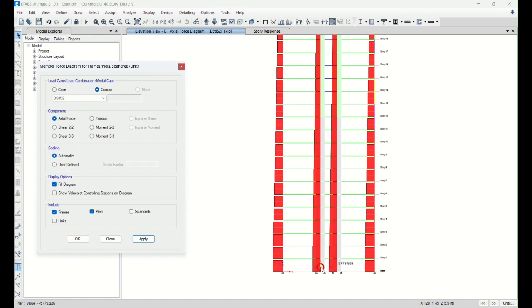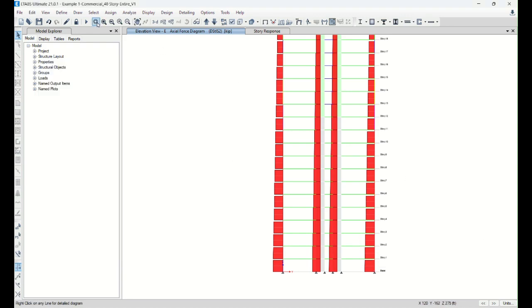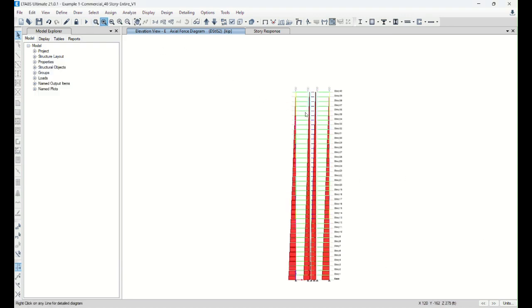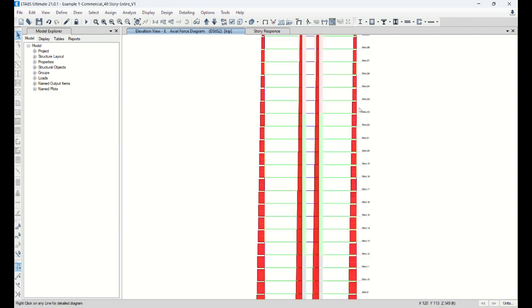This wall experiences 5,700, 5,700, 7,000, right? Something like that. But one thing I wanted to make sure of, because we're going to add additional stiffness, which is the outrigger, sooner or later. In this initial model, there is no big horizontal deep beam member or truss between the wall and the column. So all the floor loads, which are dead load, self-weight, superimposed dead load, and live load, come all the way down through the column.